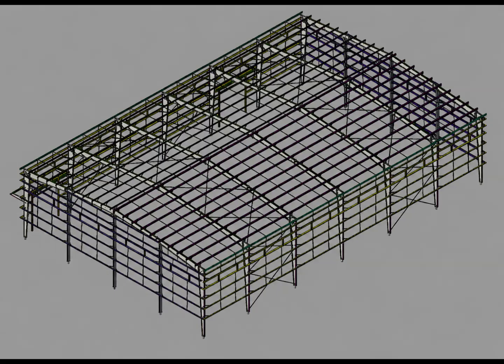Now look toward the roof again. The roof also contains its own bracing arrangement. The roof bracing connects different roof framing locations and works as part of the overall structural stability system. So, when we look at the complete PEB model, we should not think of roof bracing and wall bracing as completely separate subjects. They are different parts of the overall structural system.